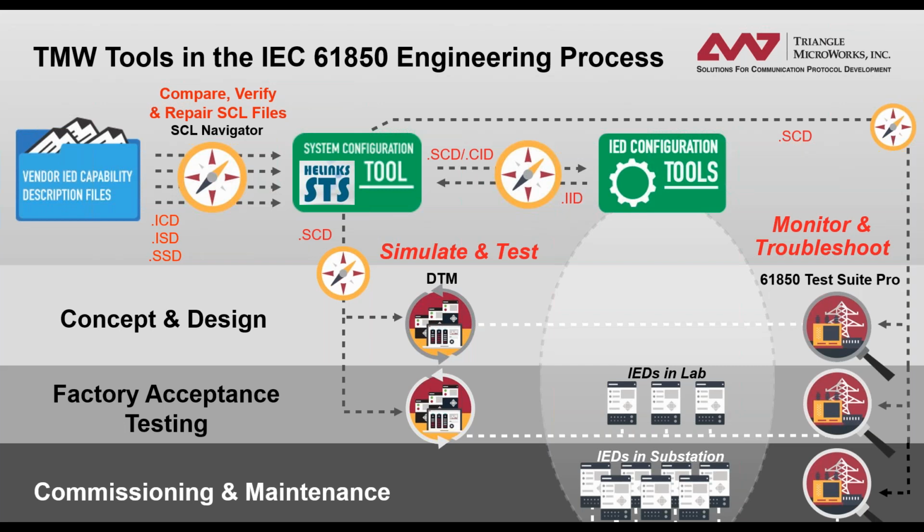Standard libraries from IEDs. What does that mean? Well, an answer that I have here from Jim Coates, who's online answering these questions, is the vendors usually allow downloading the latest versions of ICD files from their website or have configuration tools that allow creating an ICD file consistent with the configuration of the IED. Okay, so that would be the same question we had before. How do we get the ICD file?